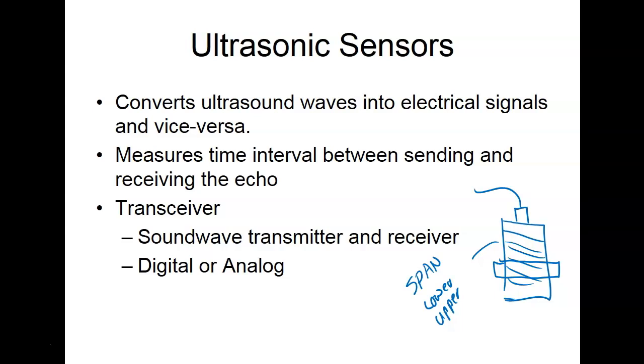But when you bring an analog sensor into a computer, the analog sensor is extremely accurate, but your computer might not be, right? You understand? Because what we have to do is go from analog to digital. So we go through an analog to digital converter, and the resolution of your converter has a lot to do with it. This analog to digital converter in this guy is what we call a 10-bit analog to digital converter.